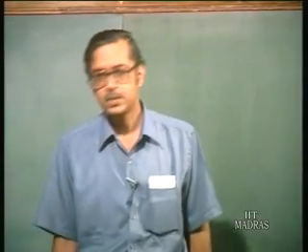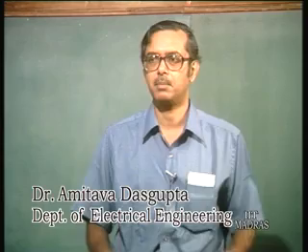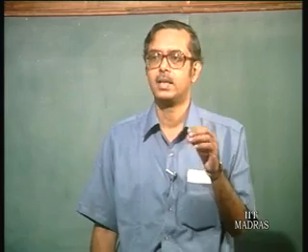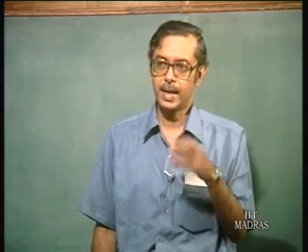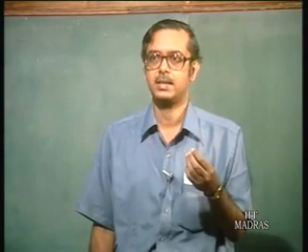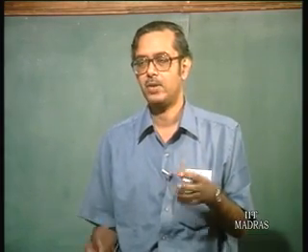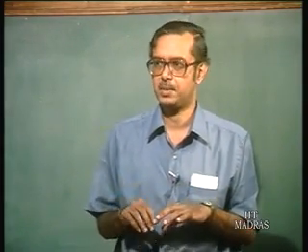So, last class we were discussing the emitter function logic, which is a variation of the emitter couple logic, and we have seen that the functionality is tremendously over the emitter couple logic, in the sense that with the same power dissipation you can realize logic circuits of much greater complexity. So, effectively you are reducing the power dissipation.